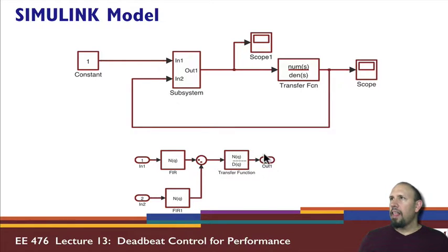This is the controller that we would use. Here I actually have it as a function of Q. The actual SIMULINK blocks you would use would have it in terms of Z inverses, so you would use the form that involves Z inverse. I've put this all into a subsystem and into this block diagram so it looks like the block diagram we had at the beginning.